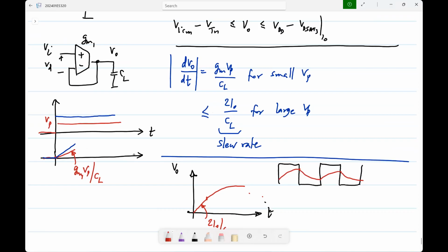So now if you had an input that is half, it may have started linearly from the beginning, so this won't be 2 times that. If it is slewing, that also causes nonlinearity. Normally in a linear circuit, the target is that and you settle exponentially. Of course, if you don't give it enough time, there'll be some error, but it will be linearly related to the input step. So if you double the step, the error will also double. So it is still a linear circuit. But if it is slewing, that error will not be proportional to the input, because some portion is spent in this nonlinear behavior. So that is the nonlinearity. Is that okay?